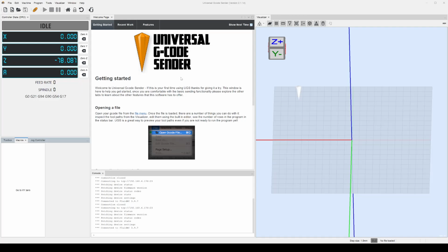This is the section I was looking for as far as the connections. You can test your connections and find different things. In Universal G-Code Sender, you can see the macros in here. This one has probing mechanisms, but it also has probing surface, like if you were doing PCB boards and such. You can set it to probe 9 points in a square of 100 millimeters and take the differences between them using G54 or G55 or whatever you have it set up for. It's a pretty good software.